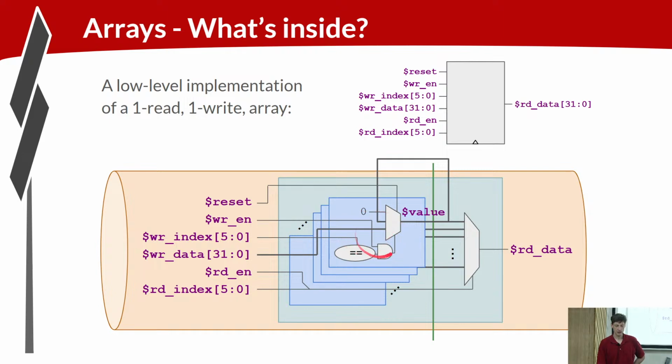So that's the write operation that happens in each value, and then the read operation is a big multiplexer across all of the entries in the structure, selected by the read index. So this is an encoded select amongst all the values in the register file. The read enable can factor into the select here, or maybe force a 0 value on the read data. It really doesn't matter. The read enable is just a power savings. If you're not trying to read data, you'd better not be trying to consume whatever is randomly coming out. So it doesn't functionally really matter what you do with read enable.